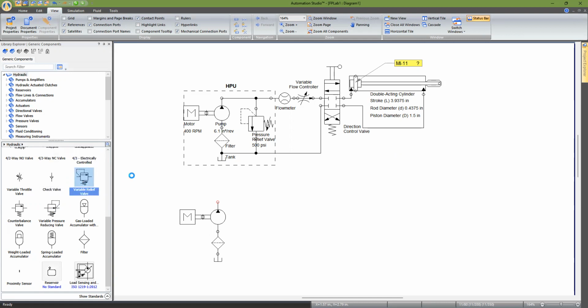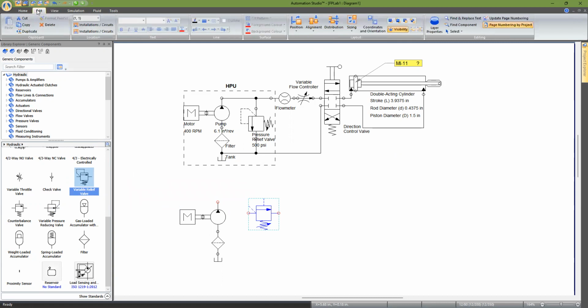I'm going to select that one and pull it over. It looks like these two have different orientations, so I'll just have to turn it clockwise by 90 degrees. Go to the Edit tab. Here's the position. You can turn them so it looks more like that, but it looks like the spring is on the right side on this one and on the left side on this one. So you can flip it about the vertical axis like this one. And then you see it looks exactly the same as this one. Now I'm going to bring it down. And here you go.